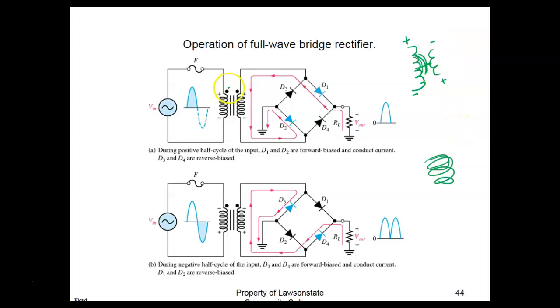So what they're doing here is they're putting these polarizing dots up here to indicate when this is positive, when this is negative, this is negative. Now on a rectifier circuit, that means nothing. Just because my secondary voltage is 180 degrees out of phase with my input voltage, it makes no difference. One thing, they're totally isolated from each other. Another thing, we're using diodes to steer it in one direction. So it works out no matter whether it's going up or down or up. But all those are polarizing dots, so they can show it like this, and don't confuse y'all.